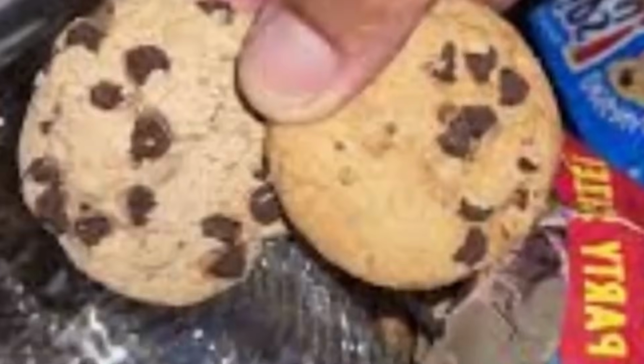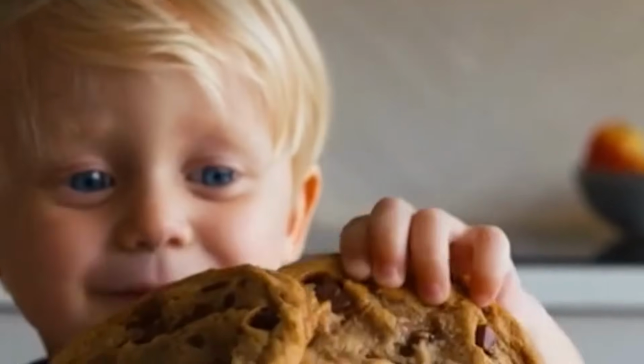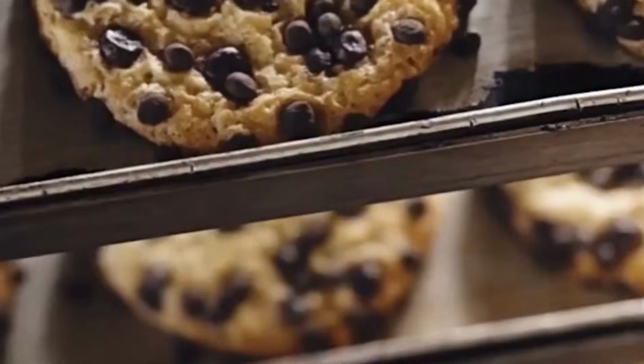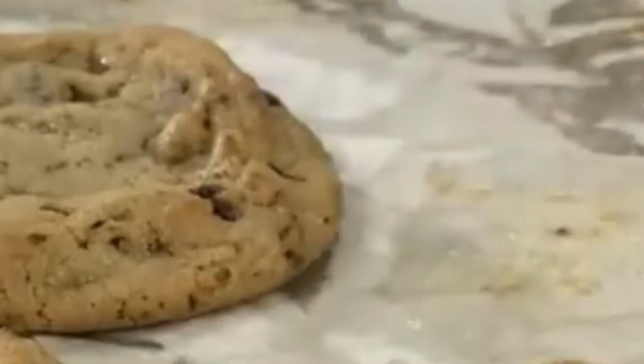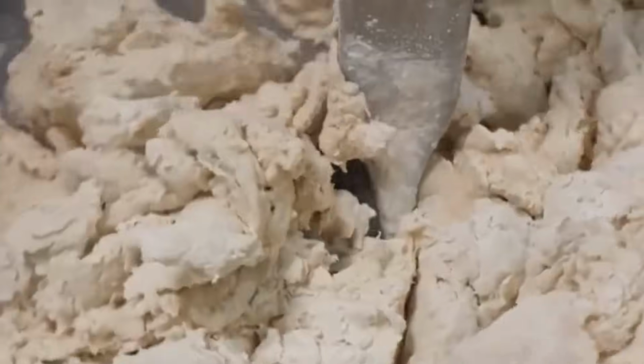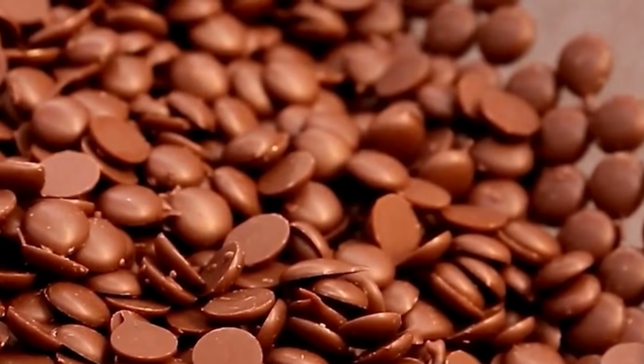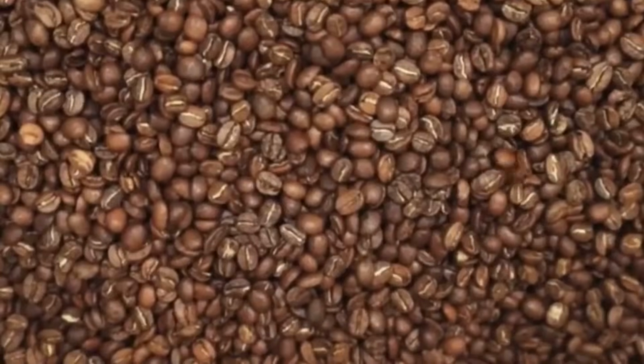Extrusion depositors are cleaned and recalibrated between batches. Nozzle calibration uses laser measurement systems to verify uniform drop size across all channels. The baking oven includes thermal profiling tools, traveling temperature probes mounted on dummy cookies that measure time and temperature exposure across zones. These profiles are compared to standard references to ensure bake uniformity.